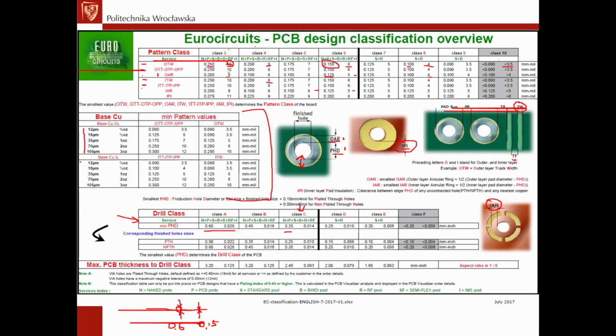The values are very strange because these are metric, and originally the copper thickness was defined in imperial units, with ounces, so there the values are round. For metric they are not really round, yet that's the way we do it today in the electronic industry.